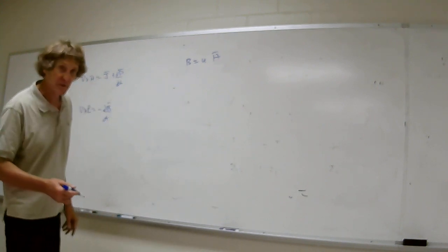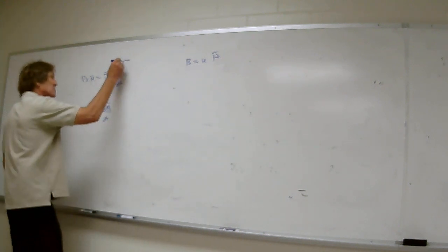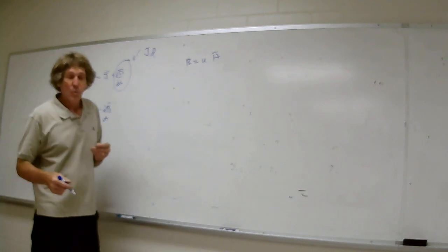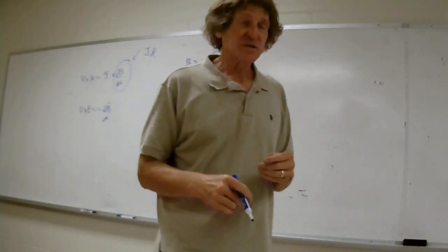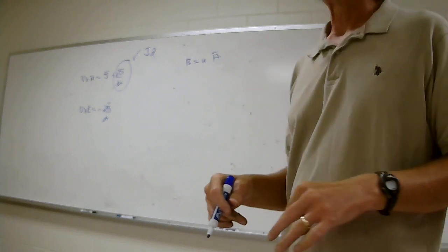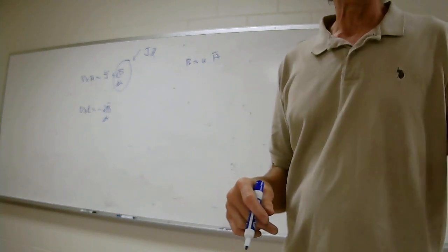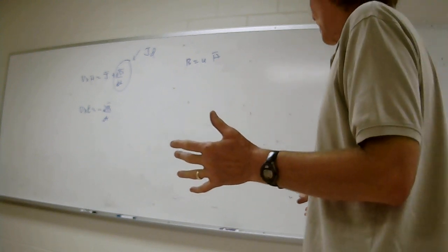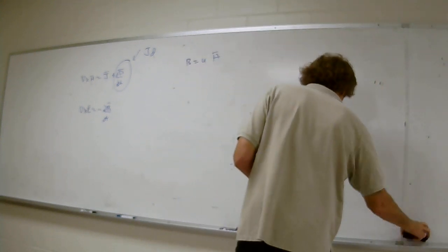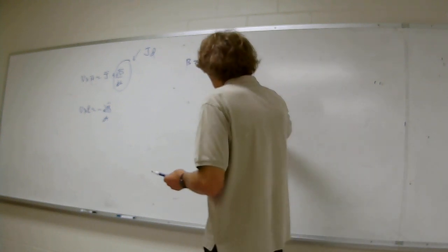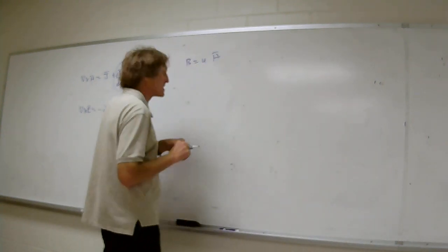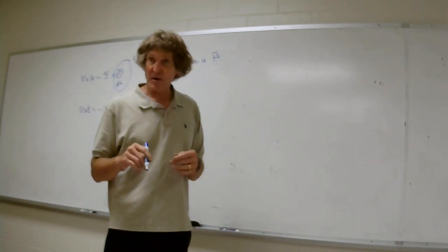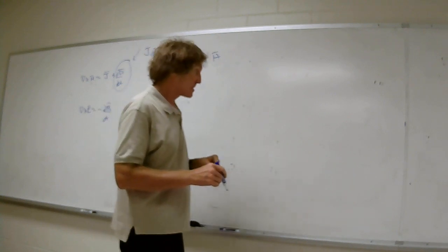Now, what is displacement current? This is it. This is displacement current density. You can just call that J displacement. What it does, and the only thing it does, is make that curl of H equation true for time varying and non-time varying effects. That's the only thing it does. So the way the book will talk about displacement current almost all the time is to try to give you a handle on what it really means. This is displacement current density. The units have to be the same as J over there. They're amps per meter squared. Y'all with me? And here's the thing that troubles.